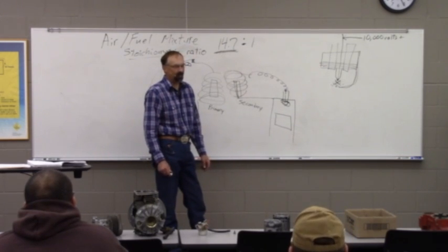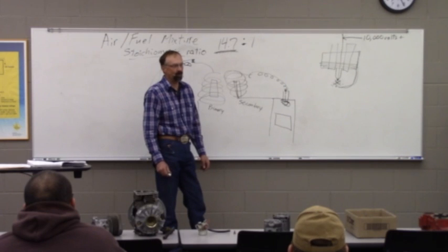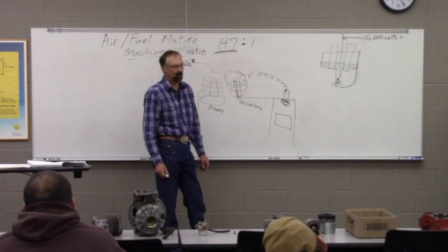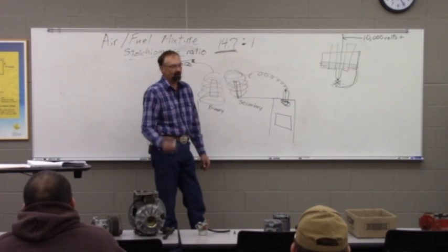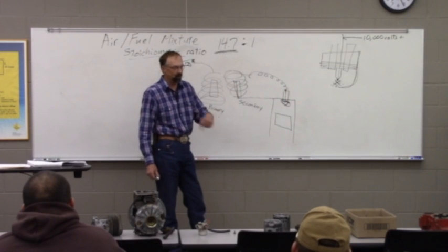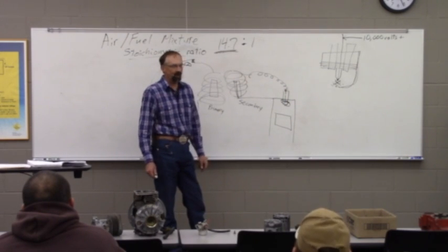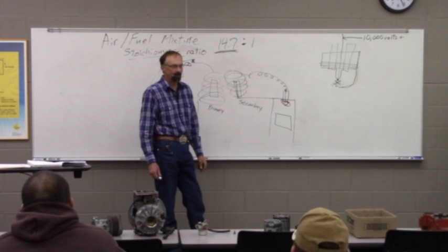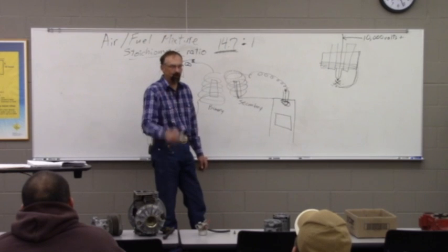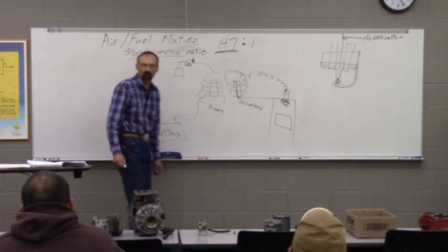There's one spark plug that I'm familiar with that the torque spec is 22 foot-pounds, and I can tell you from experience it will destroy that spark plug at 26 foot-pounds, and if you're below about 16 or something like that, within the first month it'll rattle loose and come flying out of there. And when it comes flying out of there, it takes half the threads with it, and you've got a major engine repair. So use the right spark plug and use your torque wrench if you're fooling with spark plugs, is my 2 cents worth.